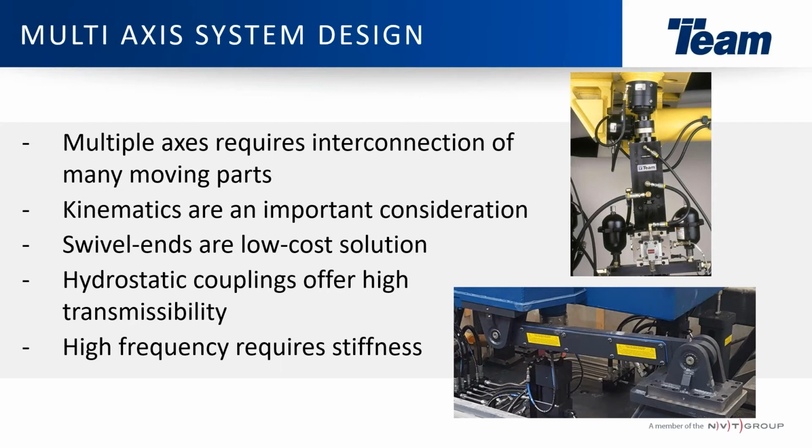One of the typical test setups for 6 degree of freedom systems is a 3-2-1, where you have 3 actuators in the vertical orientation, 2 in one of the horizontal directions, and a single actuator in the second horizontal direction. The reason for doing this is it's more or less the cheaper solution to provide the minimum amount of constraint for all of the motions.